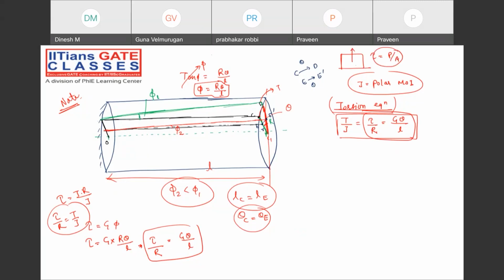Suppose you are applying one shear force parallel to the cross section, then there is a shear stress. And now you are applying the twisting moment, my dear friend. Because of that also, the shear stress will be developed. Understanding why I'm saying there are two types of shear stress? Please check it out. Perfect. It is very similar to the normal stress. One is because of the axial stress and the other is because of bending stress. The similar argument applies to shear stress also, right?